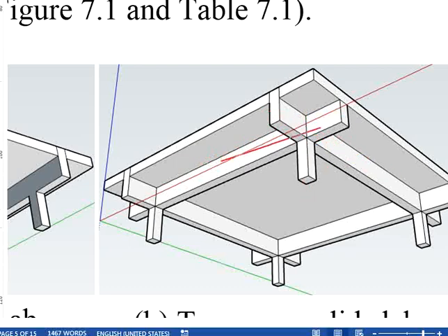There will be reinforcement from the beams, another set of reinforcement from another beam, and also reinforcement from the columns. This will lead to concentration of reinforcement at the junction here, limiting the space between the reinforcement that allows concrete to flow through in between and maintain a good bond with the reinforcement.